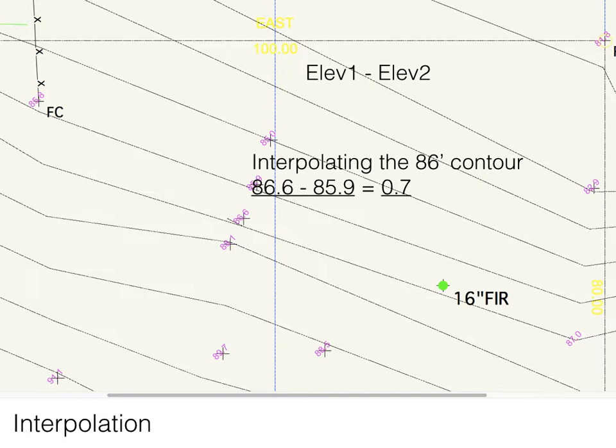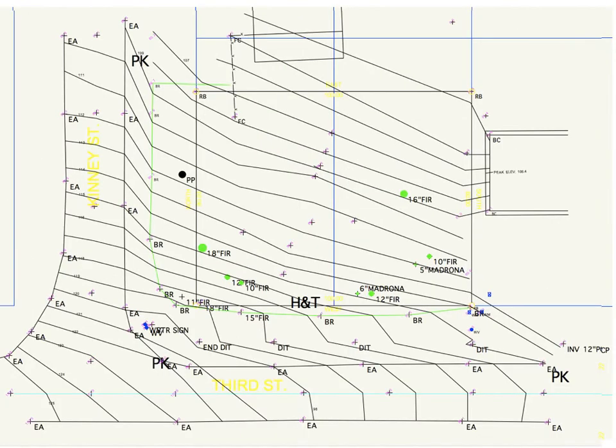And over on the right side, you can see from the 87.0 to the 82.9 spot grade, I've laid out a uniform slope there with a series of points that are like inflection lines on that slope. So this is the finished plotting of the existing topography on the site.